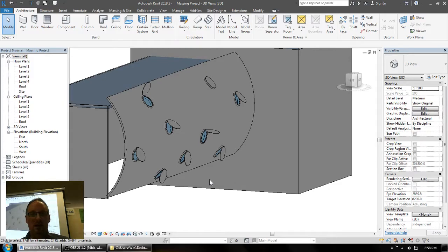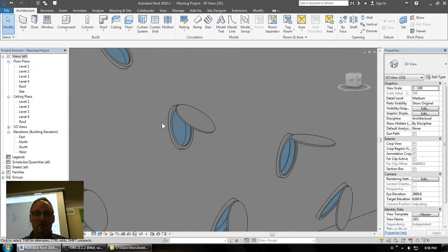So you could build your windows so that the vent frame is hosted on a reference line, and you can make that reference line angle outwards to represent an operable window. Okay, so if you folks want to save that portal window to your own folder and have that ready and just share it in to your share in folder before next week.